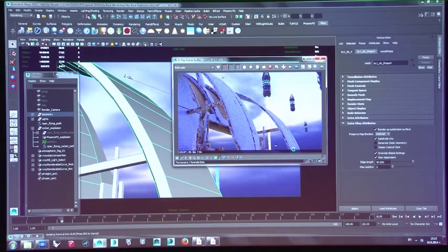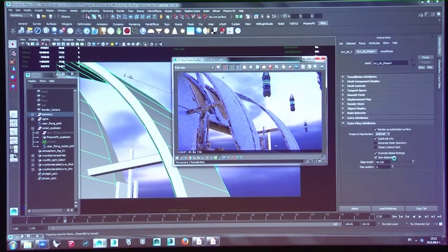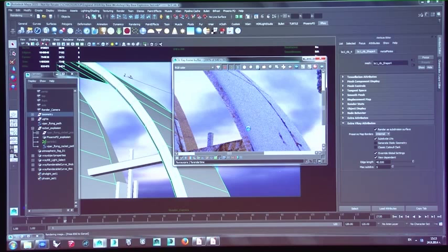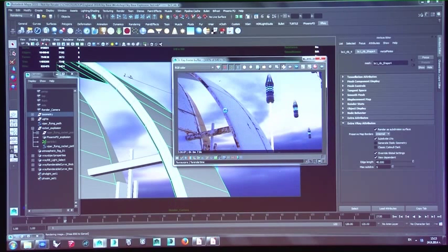While I'm rendering, I'm going to explain the second part. I have it turned on, switched to the view dependent mode, which will measure how detailed this will be. As you can see, this is now smooth. There is absolutely no edge here. By the way, I'm using yet another new feature of V-Ray 3.0, the progressive image sampling, which will give me the result of the rendering immediately, and then as time goes by, it will constantly keep refining the image, so that if I want to spend more time rendering, I can see it in better quality.